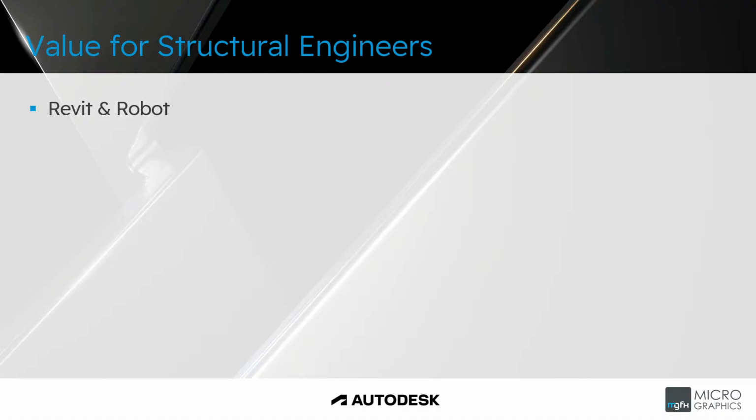When it comes to going from CAD to analysis, the workflow, in my mind a useful workflow, is only one way, and that is from CAD to analysis and not from analysis to CAD. And that's because the programs have two different modeling philosophies. On your analysis side, things work on center lines, shear centers, and everything needs to be connected.